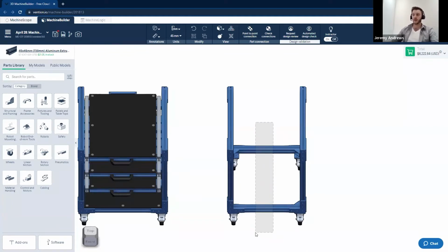You can use a drag and drop window that, if you are accustomed to other CAD software, functions the same. A drag from right to left selects everything that the window touches, and a drag from left to right selects everything that's completely inside the window. Obviously, the extrusions are not completely in the window, so I'll go back to the right to left.